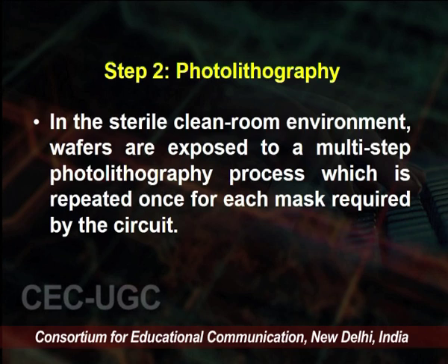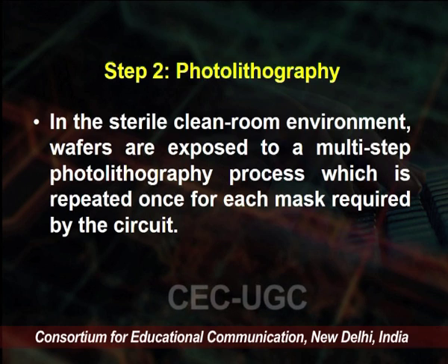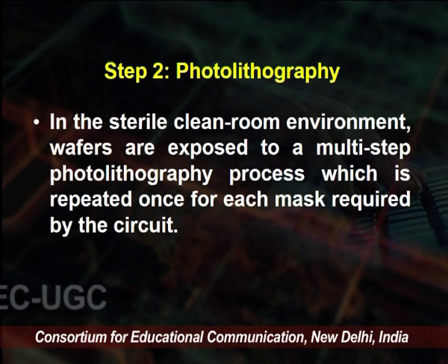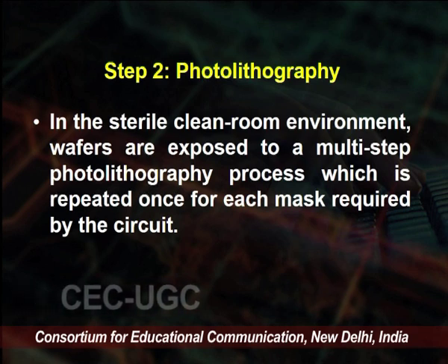That next step is photolithography. In this sterile clean room environment, wafers are exposed to a multi-step photolithography process which is repeated once for each mask required by the circuit.